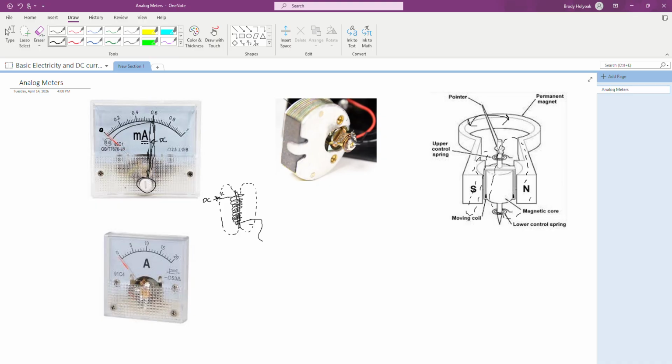Now they make these in all sorts of different kinds, different flavors. So we have milliamps, we've got microamps. We have some that we use quite often that are like 10, or 10 to 20 or 30, or sometimes even 50 milliamps. I have a couple that are 100 milliamp. So you can really get whatever kind you want, and they will just measure the value that they're indicated for. Now, obviously, if you start measuring too much, that needle is going to go past over here.